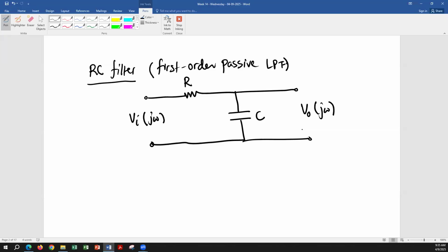Okay, yeah, it is because of the capacitor. But what quality of the capacitor is going to make this filter a low pass filter? Again, remember, what thing is changing when you're changing the frequency? Reactance. So you always have to think in terms of reactance, right?